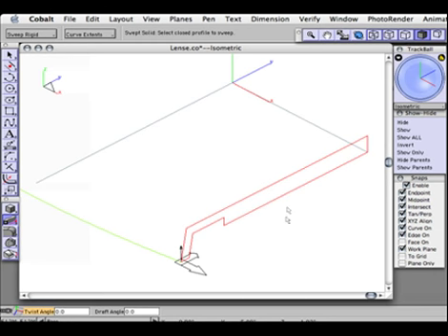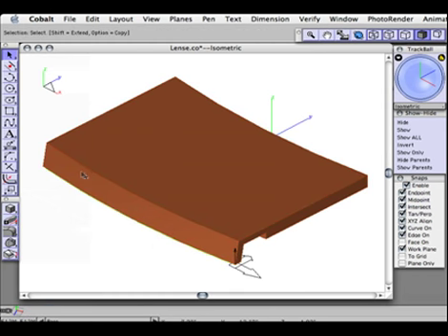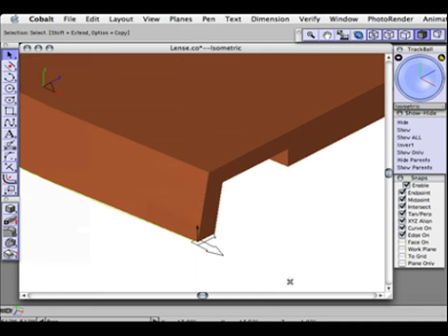With the profile selected, now I'm going to pick curves for the sweep path, which is just that arc. Once I select that, it sweeps that profile along the arc. And this creates a nice smooth extrusion along that arc. Now I'll turn the work plane off, and I'm going to blend these edges on the bottom of this part, which I could have done to the wireframe originally, but this time I'll choose to use the radial blend tool.